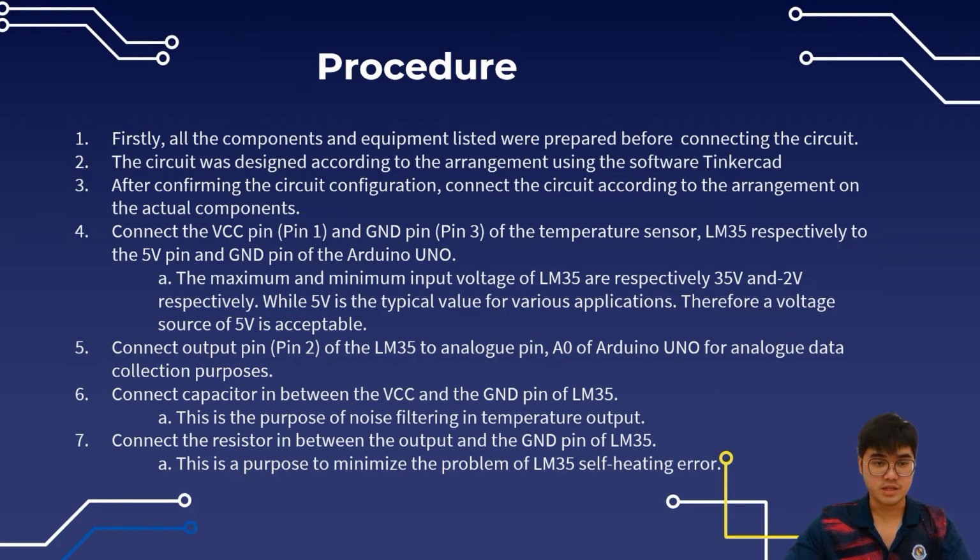Connect capacitors in between the VCC and the ground pins of the LM35. This is for the purpose of noise filtering in temperature outputs. Connect the resistors in between the output and the ground pins of the LM35. This is for the purpose of minimizing the LM35 self-heating error.